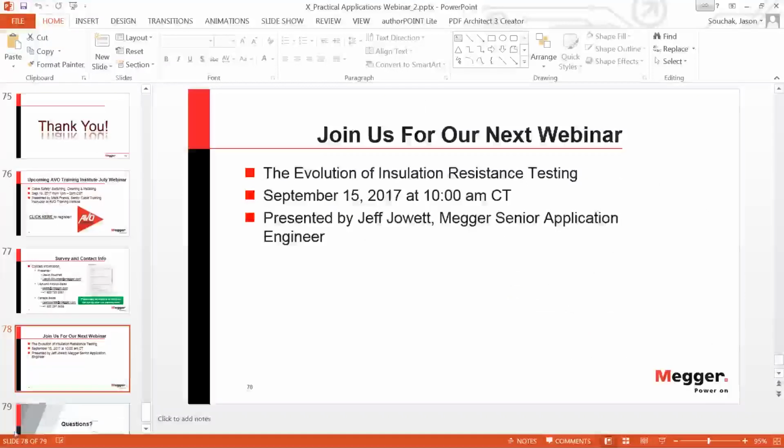Okay, first question we have is for our panelist Henning, and that question is: for which defects is DC testing blind? Typically you can say DC testing finds resistive type defects fairly well, but not defects that are more capacitive type defects like you would find in splices and terminations.